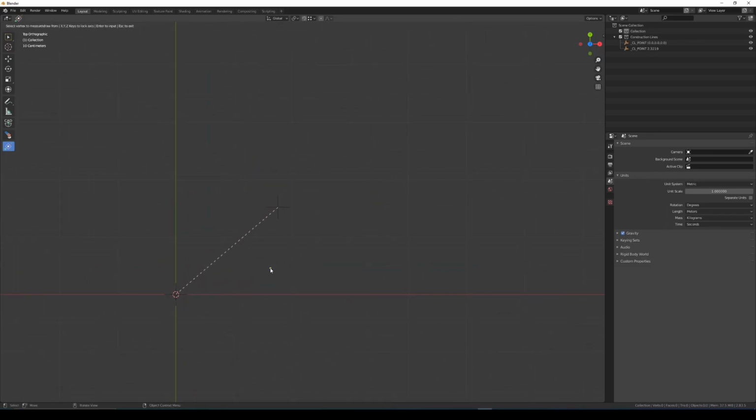The other direction is an edge extension, so finding the direction that an existing edge or guide is going in, and you can snap to that, and that will be in purple. So when I find that, it will automatically snap in that direction, and then you can type any number of courses you would normally be able to do, and you just simply extend that geometry edge or guide edge forward.